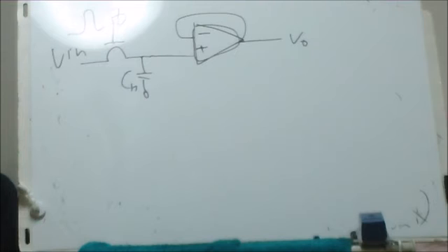The simplest is shown in this figure. A narrow pulse is applied to the gate of the MOSFET, enabling Vin to charge the hold capacitor CH. The width of the strobing gate pulse should allow the capacitor to fully charge before being removed. The op-amp simply acts as a unity gain buffer, isolating the hold capacitor from any external load.